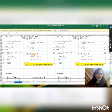So for our spacing, we have this formula: B minus 2 times concrete cover minus the diameter of our bar, all over the number of bars minus 1. Substituting the values of the variables, we will arrive at the answer of 476.37. So in our spacing, we will round it down.